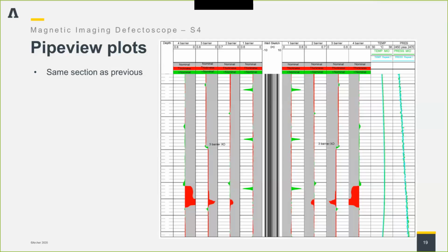most of the up to 25 chrome and things like that, even a bit higher than that, there's enough residual magnetic permeability and certainly conductivity to allow us to measure. The signal to noise ratio goes down a little bit, but we can still do that so long as they're not like completely non-magnetic Monels or something like that.